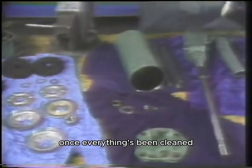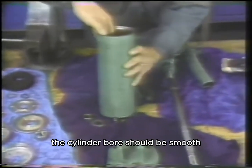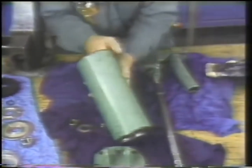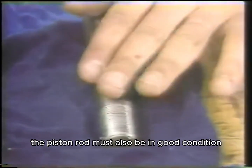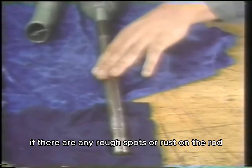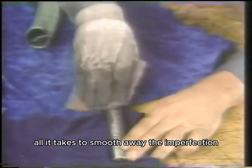Once everything's been cleaned, the parts are inspected prior to reassembly. The cylinder bore should be smooth, with no signs of scoring or other damage. The piston rod must also be in good condition. If there are any rough spots or rust on the rod, sometimes a light sanding is all it takes to smooth away the imperfection.